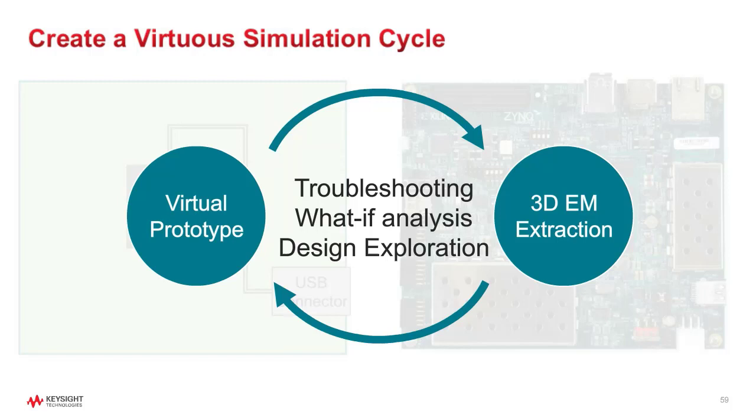And here's a question that came from Garrett. You mentioned a lot about signal integrity, SI Pro. Does that mean I can also do power integrity simulations? Yes, indeed. It's SI PI Pro. That means you can actually perform both signal integrity and power integrity simulation in the same workflow. After you import the board I'm showing here, this is a Xilinx board. Let me push to you.